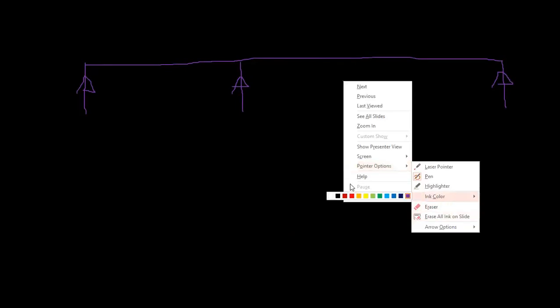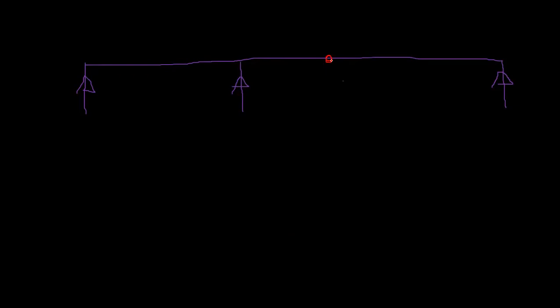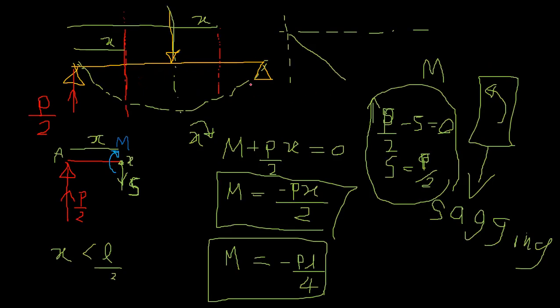Have you noticed there's only 3 equations for you to solve in the 2D case? That means if you have supports which generate 4 or 5 reactions, greater than 3, that is indeterminate, right? You cannot solve for that. Here only two reactions, you can still solve for that, right?